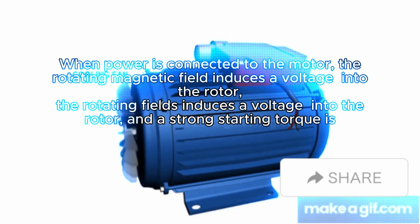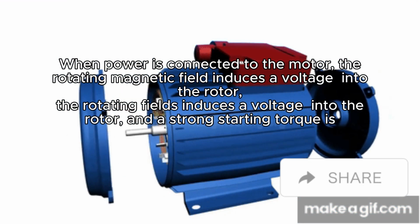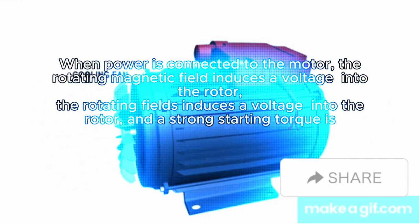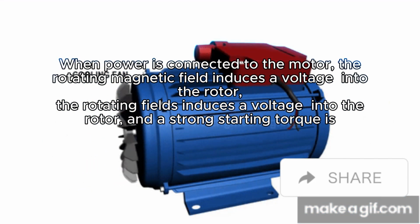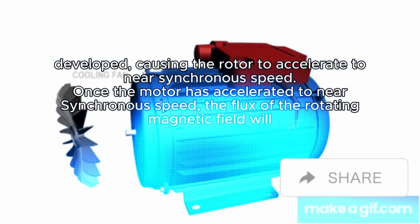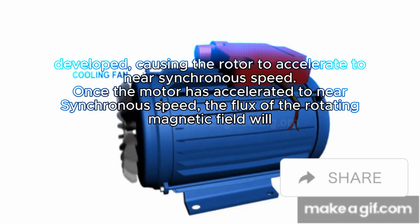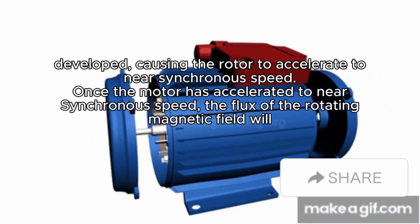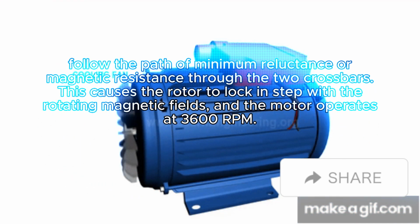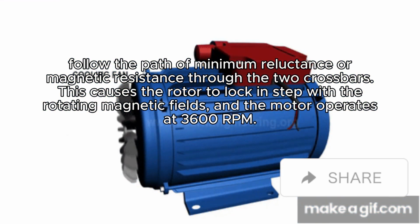When power is connected to the motor, the rotating magnetic field induces a voltage into the rotor, and a strong starting torque is developed, causing the rotor to accelerate to near synchronous speed. Once the motor has accelerated to near synchronous speed, the flux of the rotating magnetic field will follow the path of minimum reluctance, or magnetic resistance, through the two crossbars.